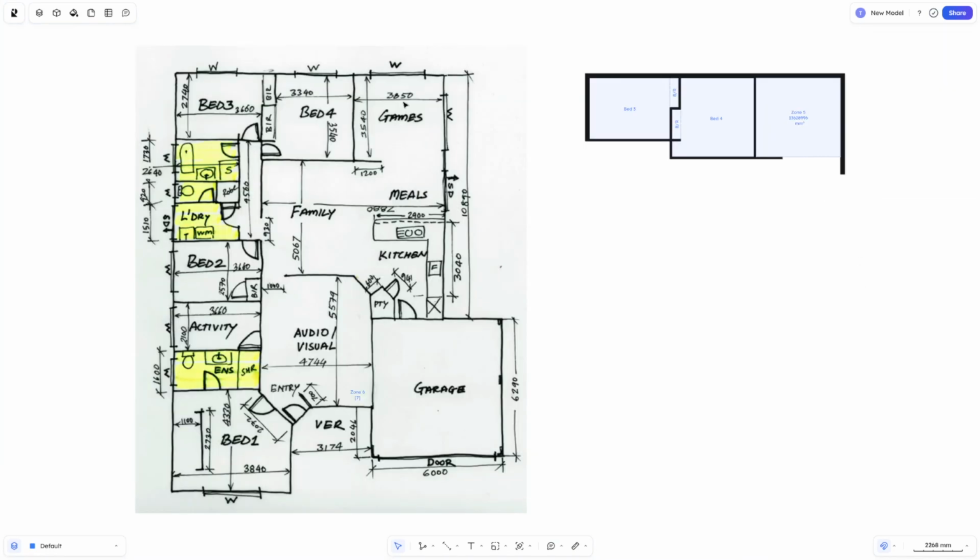So if we shift F, so we get in, we're drawing this wall down here. It's got an extremely large window in here. Before it's got a bit more wall, standard door width, and we're heading into the kitchen. So when we come to drawing floor plans, the next bit we've got to do here is this substantially large section here. Now it gets a little bit tricky when we start working out some of these measurements here, but I'll show you how we're going to do that.